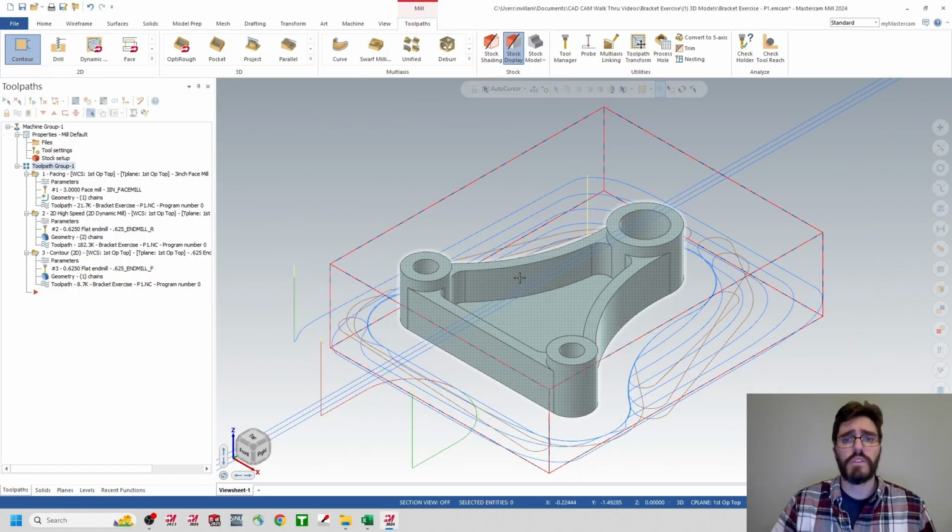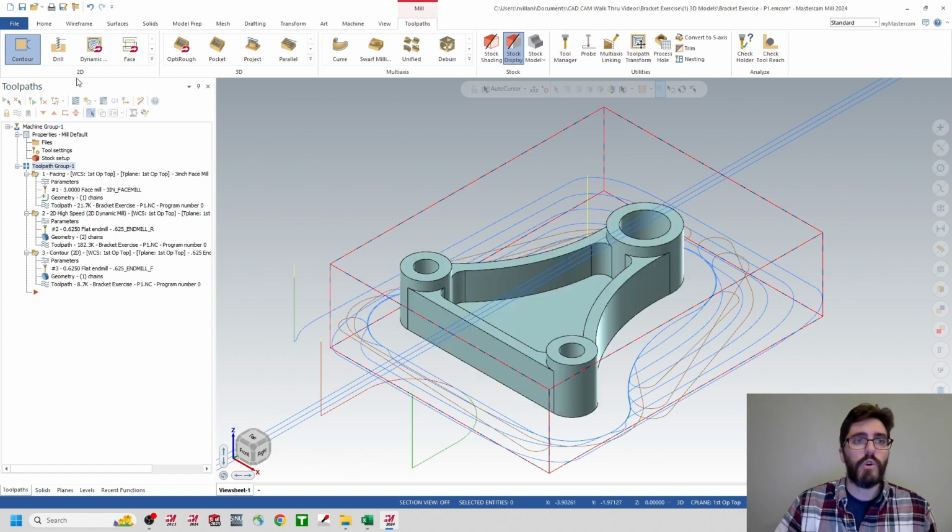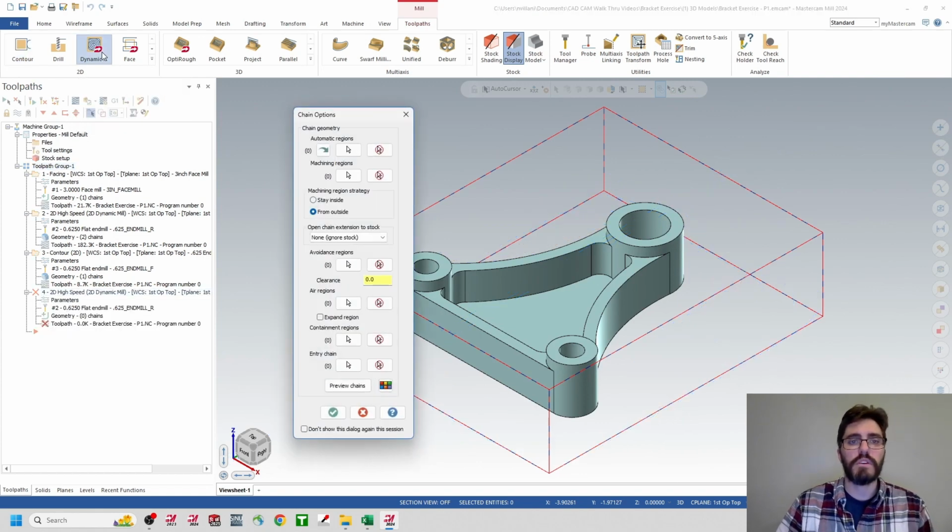And then we can move on into our next toolpath, which is actually going to be this step here from the top surface. So we're going to go down one step, and I think we can go ahead and use the 2D dynamic mill once again. So we're going to remove this top step here from the top surface to the step. So we're going to go over here to the 2D gallery. Inside the 2D gallery, we're going to click on 2D dynamic mill.